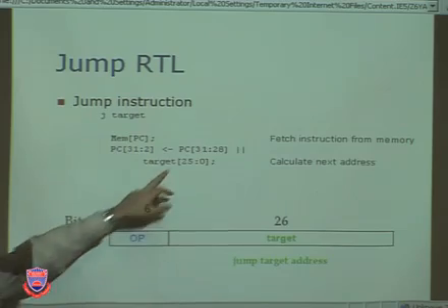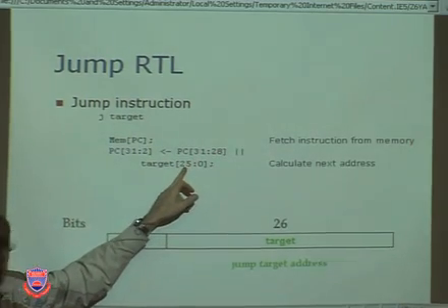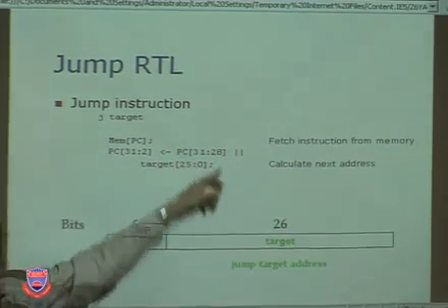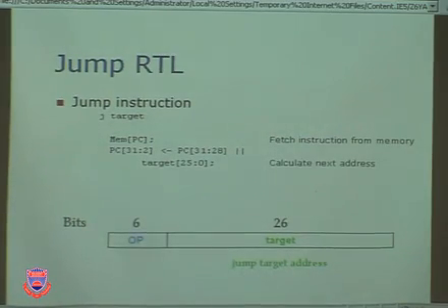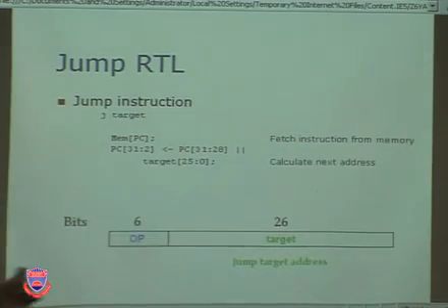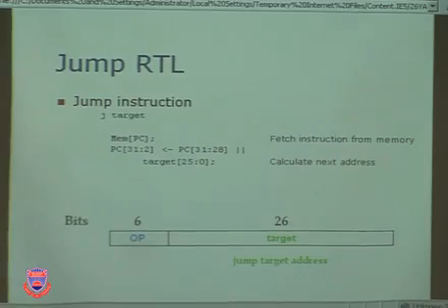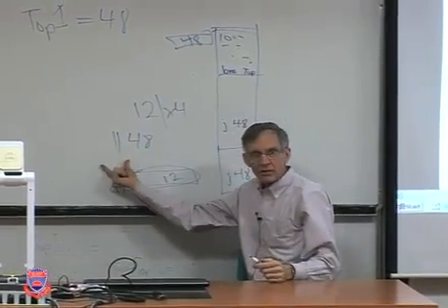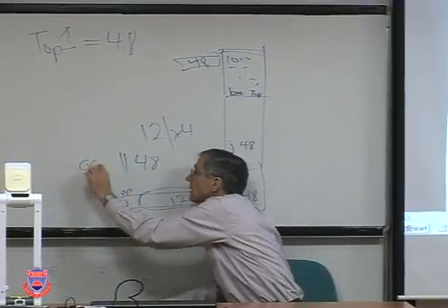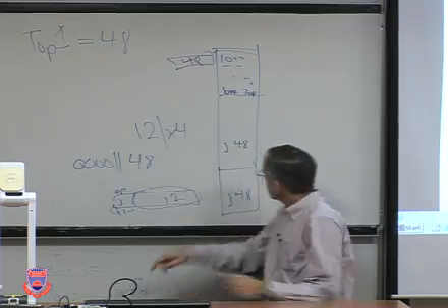Okay, you can see that this is the upper 4 bits. This one starts at a lower place. The grand total of those concatenated together is 30 bits, right? There's 4, there's 26. Paste them together, you have a 30-bit object, okay? So that means that this needs to have concatenated to it that much, right? Okay, so we go to that.